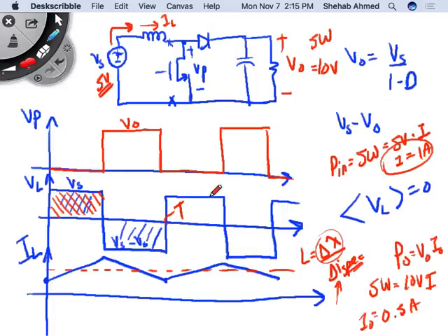But assuming you're given your switching period and you know your duty cycle, because duty cycle is what you need for the voltage transfer ratio. This is independent of switching period. So you will select your duty cycle first. This is something you know. Then you can play with the switching frequency. Okay, let's set the switching frequency at 50 kilohertz. Then I can draw this waveform. If I draw this waveform, I can calculate the inductance needed at a specific switching frequency for a specific ripple current. Right? Because I know where this is.